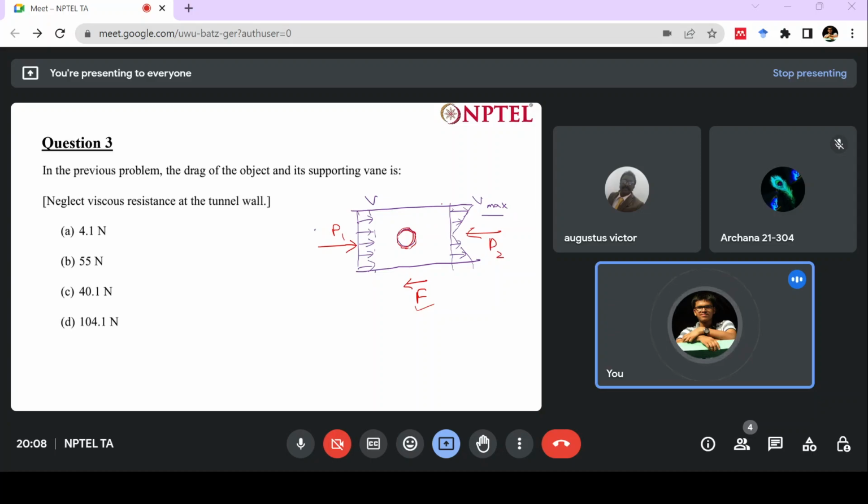I can find the flow field at the exit, supply my flow field at the inlet, and from there, using the Reynolds transport theorem, we can find out the force that is acting on this object. Or in an experimental setup, there are pressure sensors which can find the force exactly on the surfaces of this ball. So this is a typical wind tunnel setup.